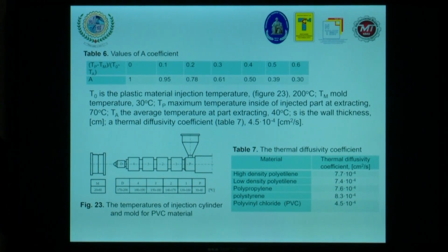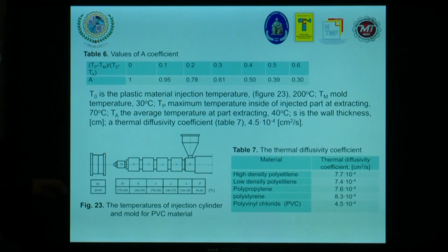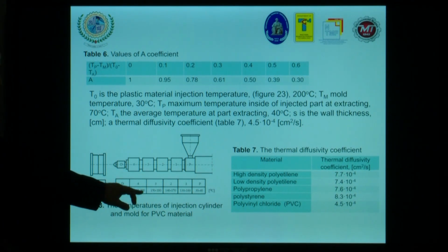It is the melting temperature of the material. We use values between zones, even though the technical literature makes some kind of recommendation. Look at the nozzle, look at the first zone, I mean the fourth zone. How can we choose the temperature here? We can choose 200 and we can choose 190. I think this is the best solution.